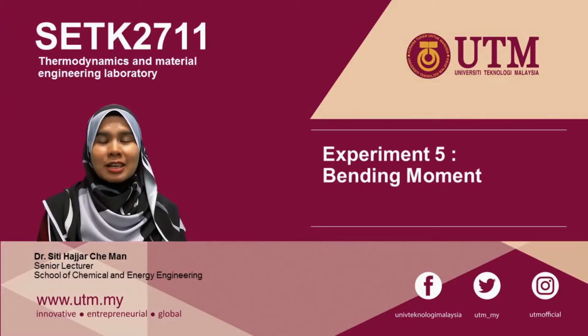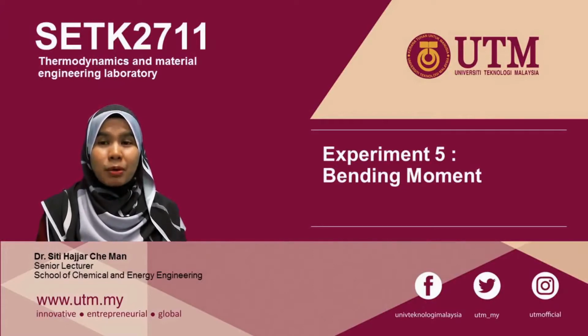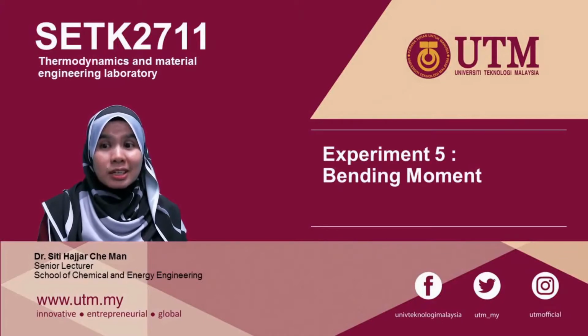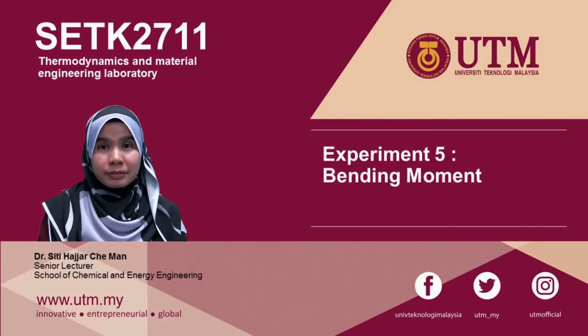I am Dr. Siti Hajar and in this video I will explain how to carry out the bending moment experiment. A bending moment is a measure of the bending effect that can occur when an external force is applied to a structural element. A moment is a rotational force that occurs when a force is applied perpendicularly to a point at a given distance away from that point. It can be calculated as the perpendicular force multiplied by the distance from that point.